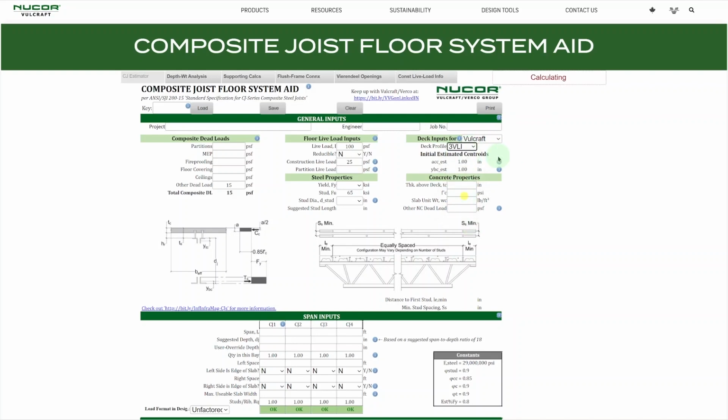all of this is going to be used to determine what the volume and the subsequent weight of the wet concrete is that the joist has to carry non-compositely before that concrete cures and it can act in a composite manner. So all of this here, we'll figure a 3.25 inch slab topping, so 6 1/4 inch slab altogether, 3,000 PSI concrete, slab weight of 145, so just normal weight stuff.